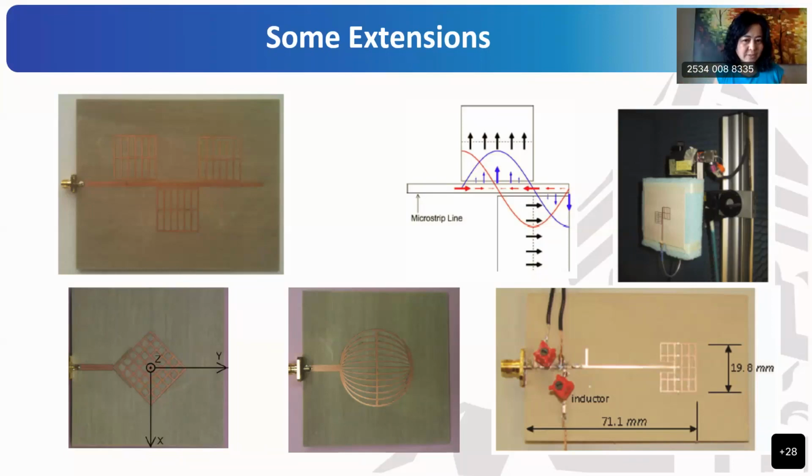And then moving to the top right, that's where you see again two meshed antennas that we assembled to give current paths in two vertical, perpendicular directions, that allows us to make a circularly polarized meshed antenna. So a circularly polarized transparent antenna that we integrate on solar cells. The bottom left is again a circularly polarized meshed antenna.